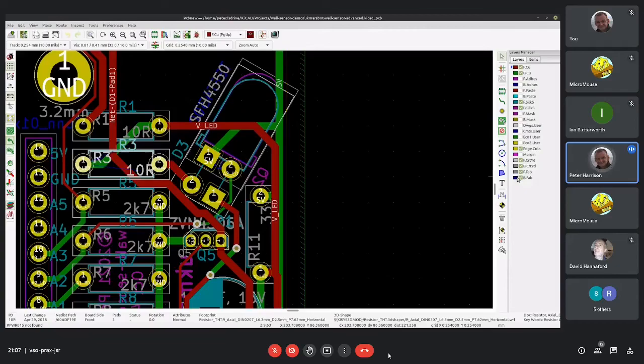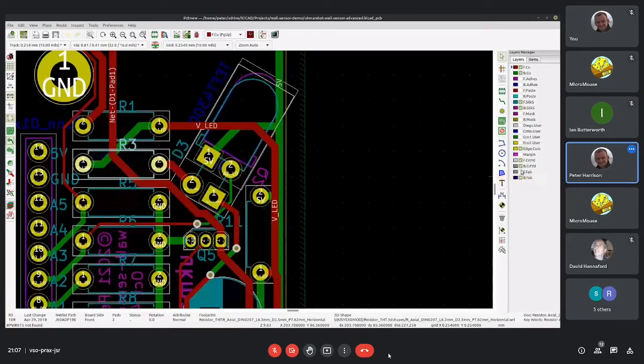Or you can print them out or whatever to say where stuff goes, but that information doesn't need to go on the board. So let's get rid of that. What you do need on the silk screen usually is the component identifier, right? This is D3. Upside down here on the back of the board is Q2 and so on. So we'll leave that on.